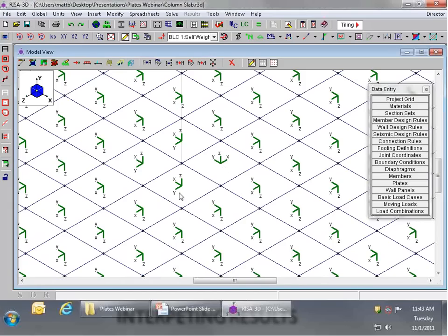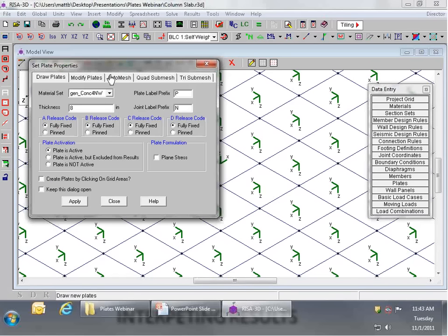Now this can cause us issues. For example, the local x-axis of this plate is different than the local x-axis of this plate. And so if I start comparing values of, say, our f sub x, I can't directly compare the values back and forth between this plate and this plate because that value is reported local to the plate. But I can come in and correct these values at any time.